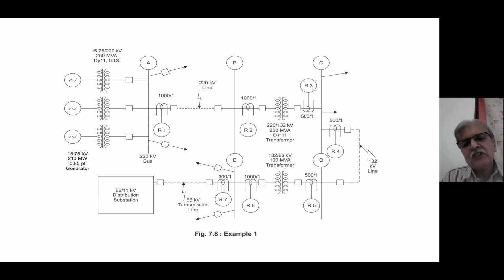And as per IS, plus or minus 7.5% beyond PSM 4 you have to allow. That is time error of relays you have to allow. R6 may operate earlier, R7 may operate later. You see, that is quite possible. Second thing, R7 operates means fault is not cleared. You have to allow for breaker time. Breaker will take its own time, no doubt.